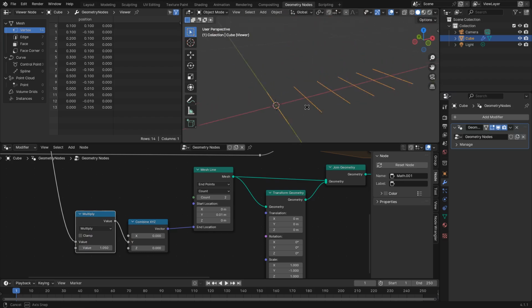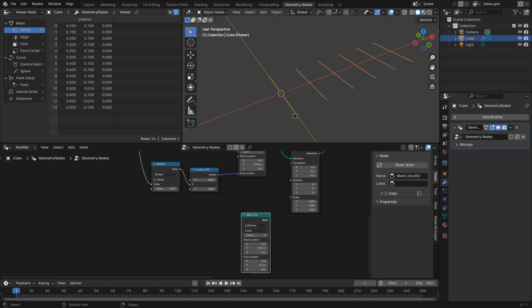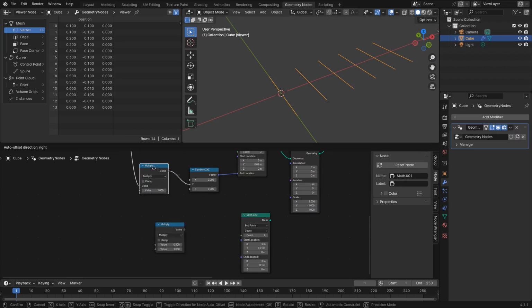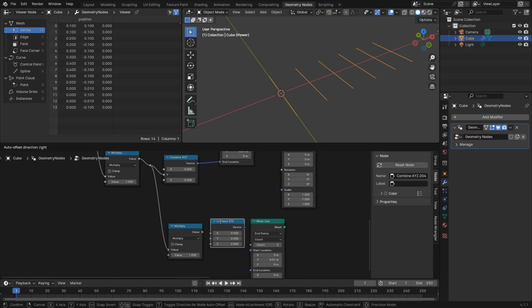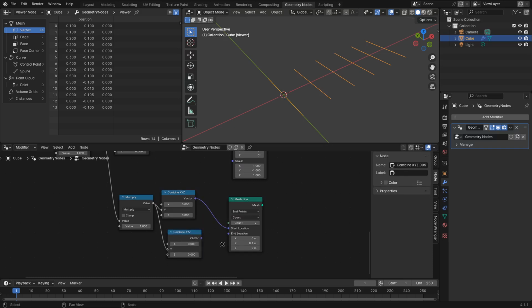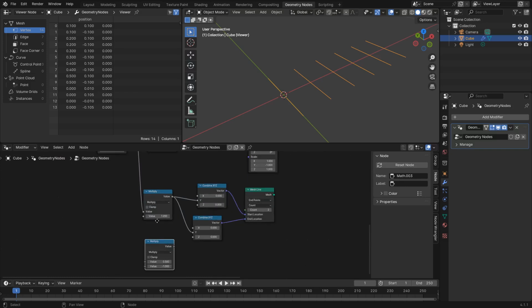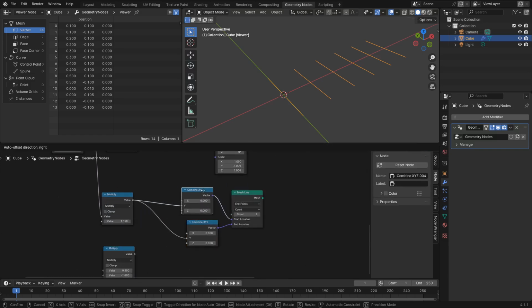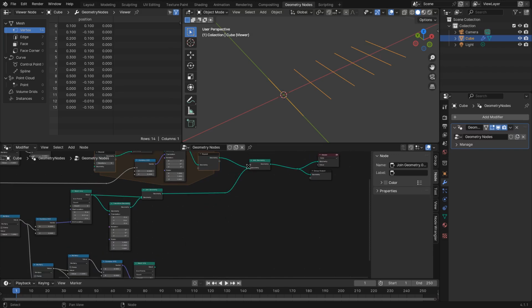Okay. And now the final part is we need to add a reflector at the back. We are going to use a mesh line again, and then we are going to make it again 5% wider than the driven element. So let's use this again. Let's use the output of this. Combine. This time we are going to use it on both directions. So let's go like this, like this. Reuse this one. And join it in here.